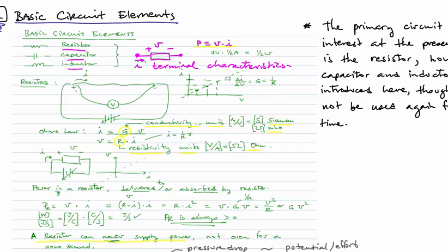What is the relationship between those two? And what defines a resistor then is an element that if you apply a voltage across it, so here's voltage, and here's current, I'm going to plot current versus voltage. If I apply a voltage across this element right here, and I measure the current and I get some current, and if I do this again but for a higher voltage, and I get a new current response, and it's this point, and I continue doing that, eventually I will find that all those points lie on a straight line.